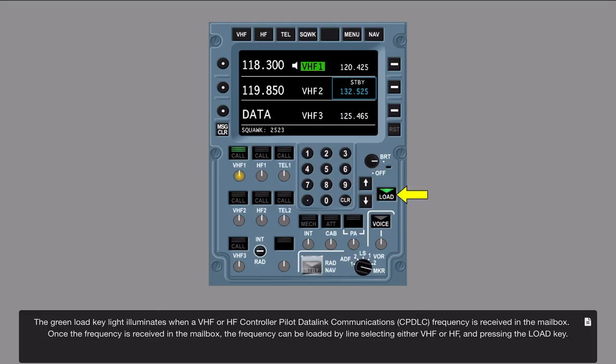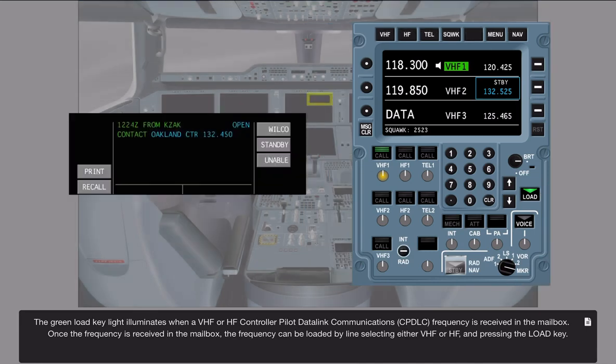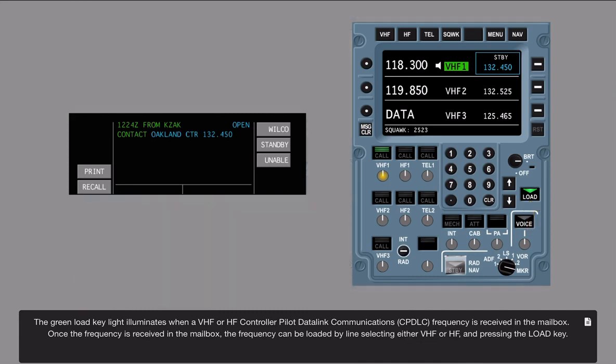The green load key light illuminates when a VHF or HF controller pilot data link communications (CPDLC) frequency is received in the mailbox. Once the frequency is received in the mailbox, the frequency can be loaded by line selecting either VHF or HF and pressing the load key.